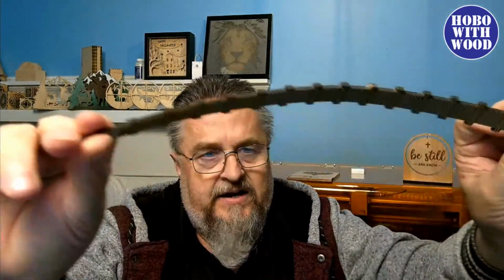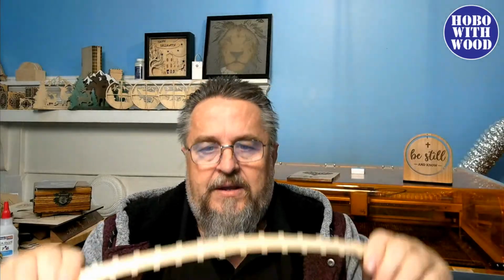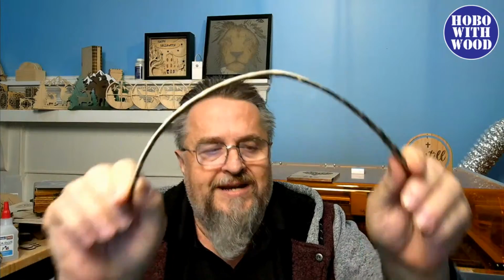This side, I didn't cut all the way through. I just cut halfway through the material, and it's not focusing very well. And then with some steam and some heat, I was able to get this to flex and twist and take the correct arch, and I could have glued that into place, and that would have been a much more finished looking piece. Living hinges aren't unattractive. They have their own look, but I thought this would be a cleaner look. So I'm still working on it, but I had to put that one on the back burner.